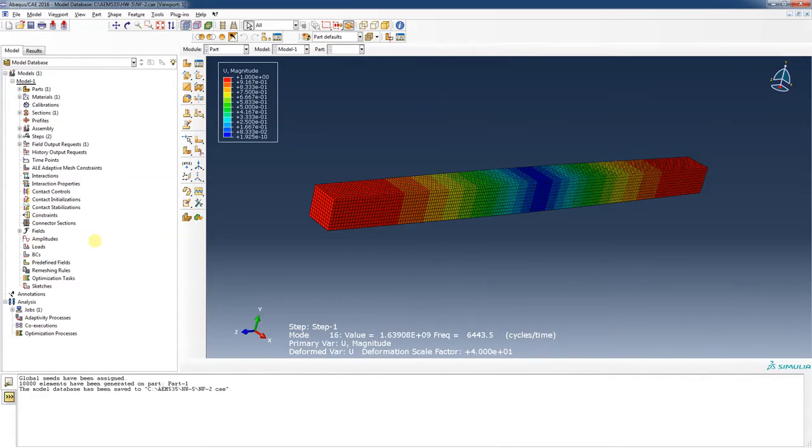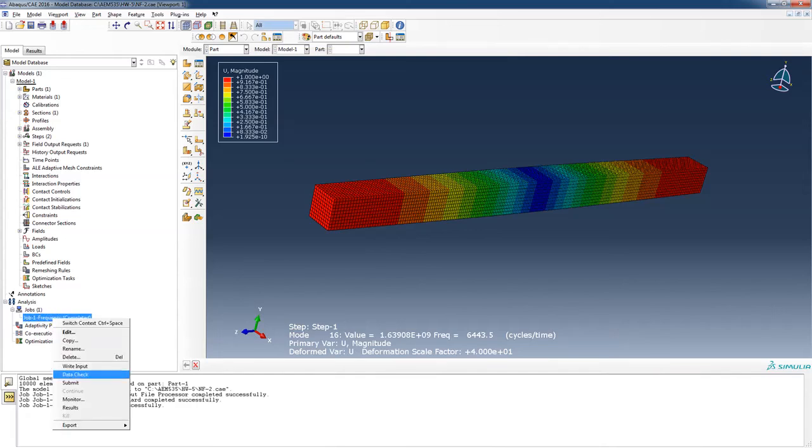All right. Everything that I did, including submitting the job, so I probably overwrote my job, is running right now in this script. And you notice it says down here, it has saved the file to nf-2.cae. So it's really important to make sure that you change that name. Now apparently before the job completed, it went and did the post-processing on the old file. So I guess you should be a little careful about that. But let's look at the results.